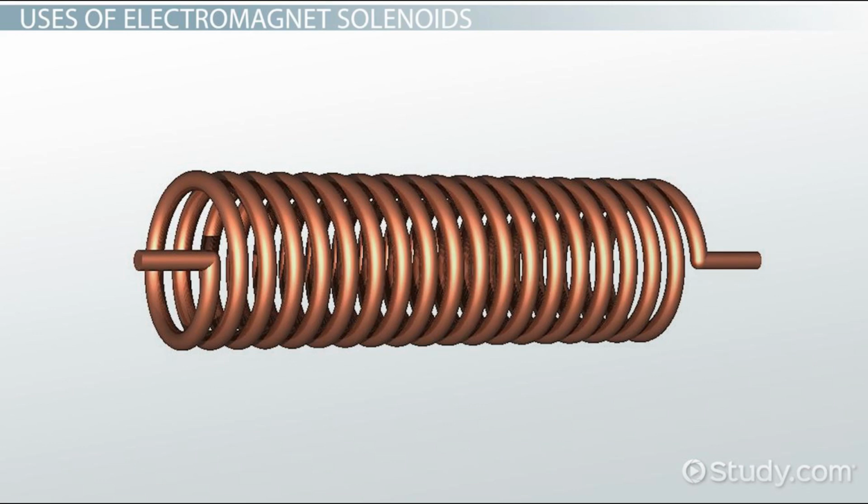Precise control. Rotary solenoids provide accurate and precise control over rotary motion. They can be designed to achieve specific angles of rotation and allow for precise positioning, making them ideal for applications that require fine adjustments or precise movements. Compact size. Rotary solenoids are relatively compact in size compared to other types of rotary actuators. Their compact design allows for easy integration into space-constrained systems or devices where size is a critical factor.